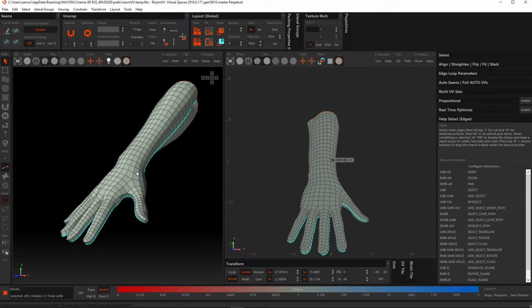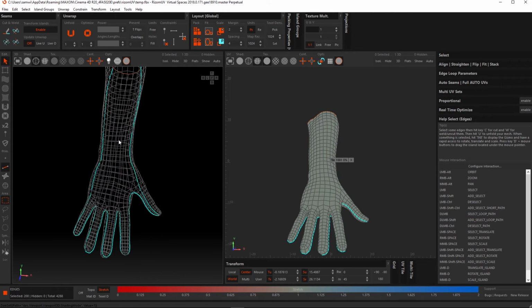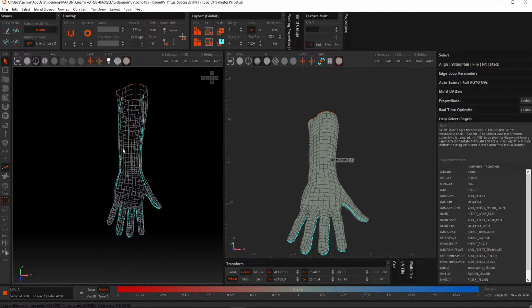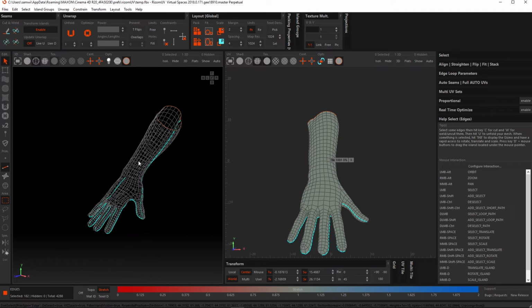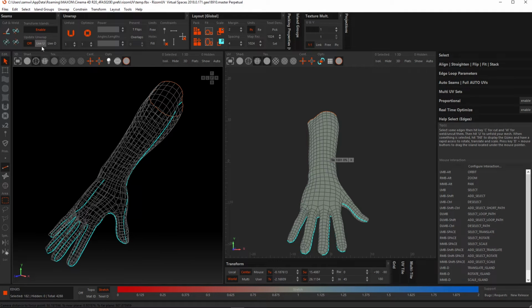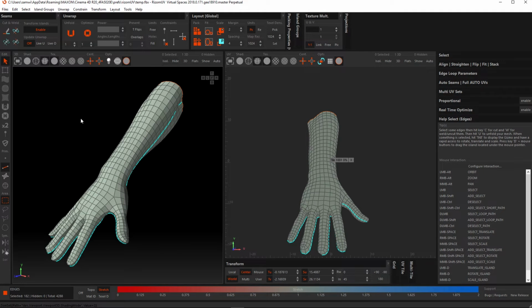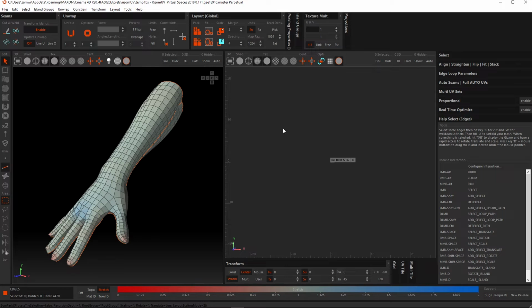And to better demonstrate my point, I'm going to go into wireframe view and unselect some of the edges. So we've got wireframe view there. And I'm going to control drag to unselect these points down to there, and return to the shaded view. So let's now cut our edges. Then unfold, and also frame our object in the UV view by hitting F.